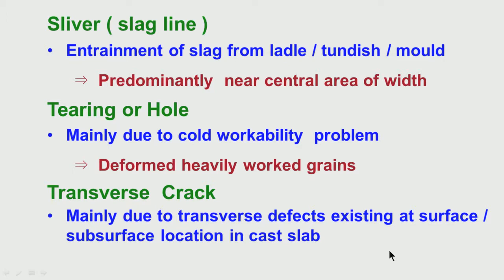Sometimes you find only a crack with no entrapment, and a crack means there will be some internal oxidation, because when the crack comes to the surface, some oxygen will get inside. So, you will get some scale, grain coarsening and internal oxidation. So, whether cracks are present on their own or along with large entrapments, that is what is important to identify the genesis of the problem.